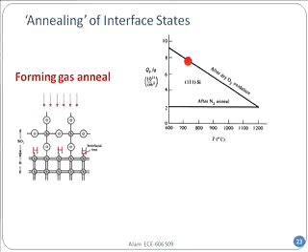But here it's a 111 surface and you have that certain number. The interesting thing is that if you anneal it at a particular temperature, and anneal simply means heating it up, just putting a piece of silicon in a chamber and raising the temperature of the furnace, like in a microwave, then essentially the number of defects will go down. These are essentially broken silicon bonds which are about to react with oxygen that was coming down but didn't have a chance to. So high temperature helps in the reaction process.